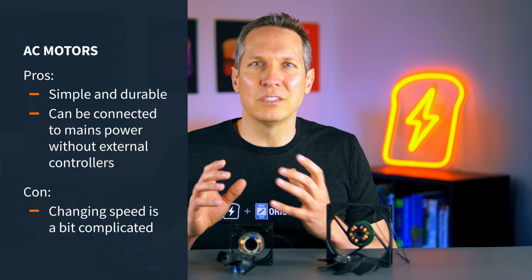However, if you want to change the fan speed, things are a bit more complicated. For smaller motors like this, you can use a triac or variac to change the duty cycle or voltage of the AC power, while for large three-phase AC motors, you could use a variable frequency drive. Also, due to the nature of the setup, AC fans are typically heavier for the same power rating as their DC counterparts, and they also have lower starting torque. Three-phase AC motors that you find in industrial settings actually mitigate some of these drawbacks and are quite efficient and powerful.